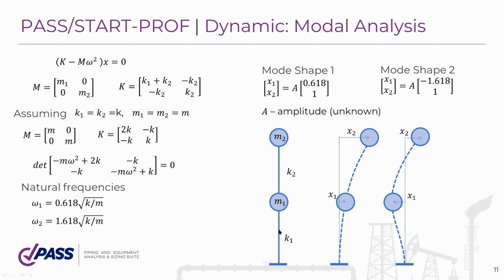We can perform the same simplifications and transformations on these equations. Also, we can assume that masses are equal and stiffnesses are equal. It will allow us to simplify this problem. The solution can be obtained from this equation. It means that the determinant of this matrix should be 0. I will bypass the complex computations and just show you the result of this solution.